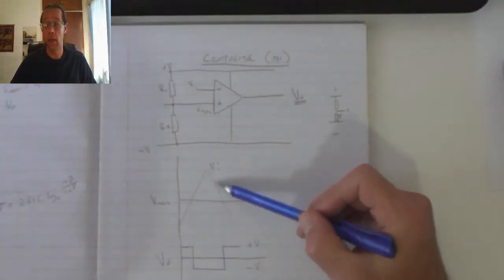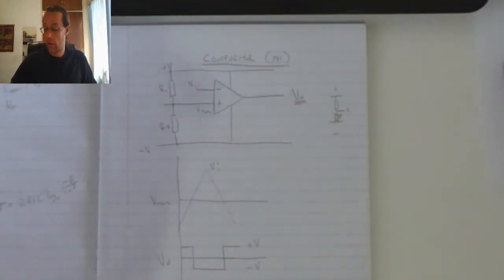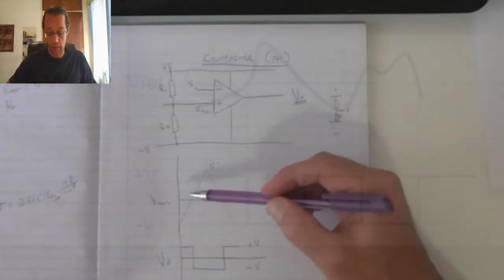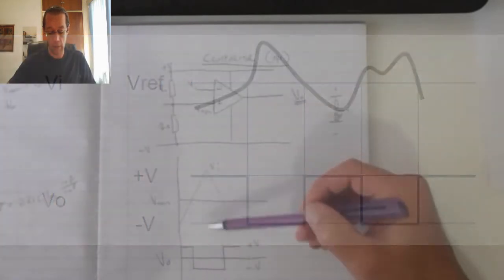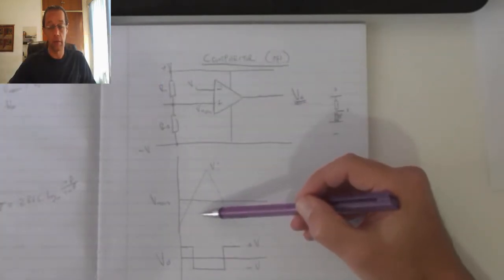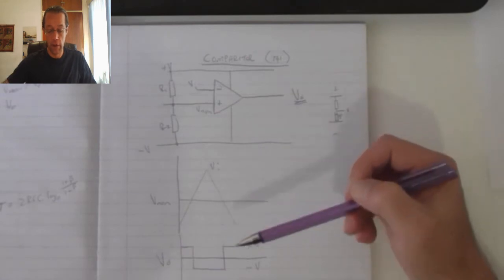This input signal can be any signal. You can connect it to a microphone if you want, but that will be my cutting limit. Anything above that, I will have a negative voltage on the output, and anything below that I will have a positive voltage.